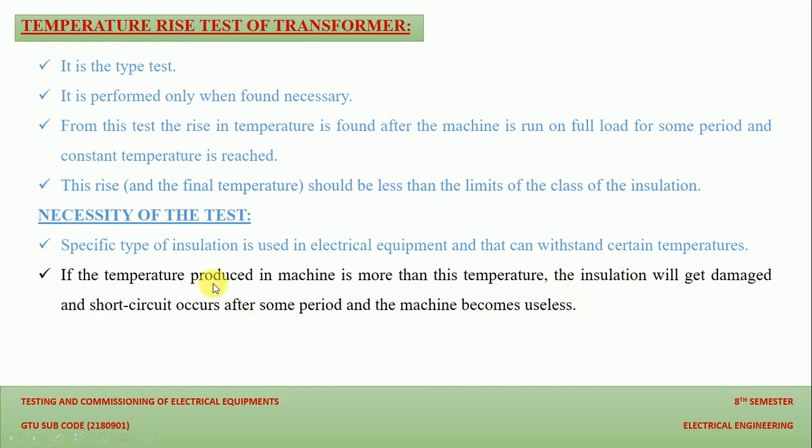If the temperature produced in the machine is more than the desired level, the insulation will get damaged after certain use, and a short circuit occurs after some period and the machine becomes useless.